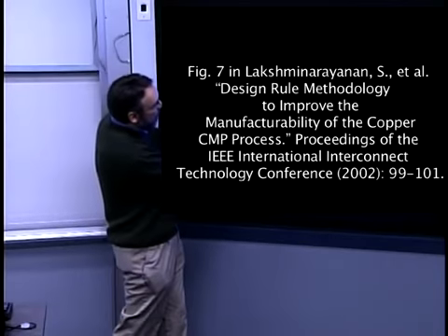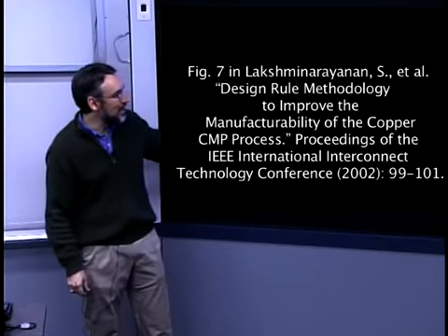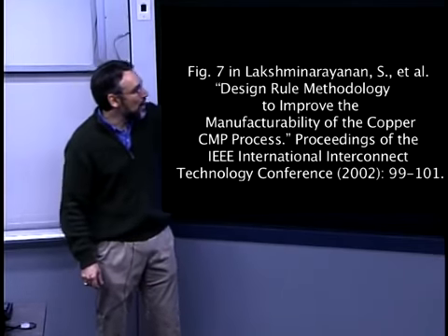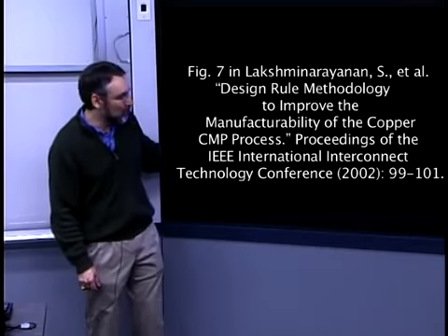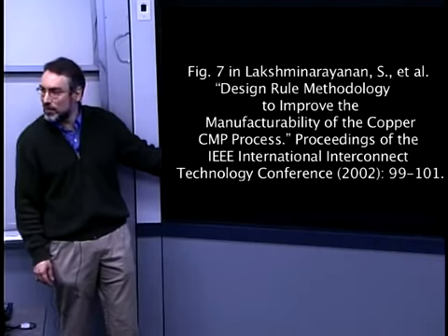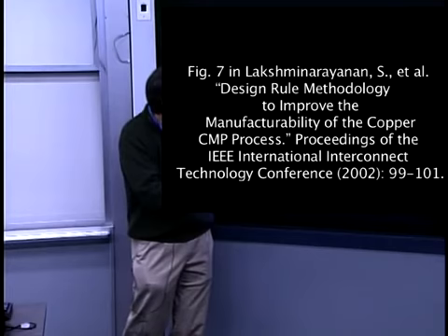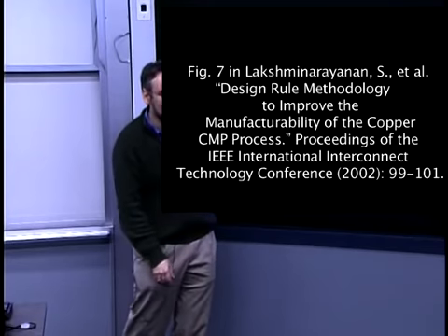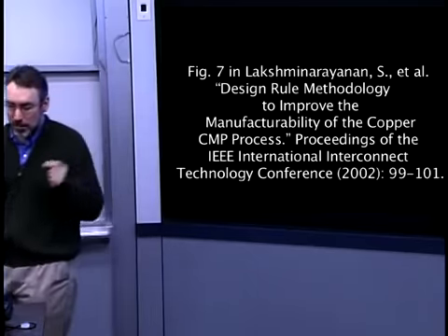okay, what region, what limits, what combinations of line width and line space can you have, and where are the boundaries because of some of these different physical effects? So, for example, photolithography says I can't pattern smaller than certain dimensions. Dishing limits, that dishing down into wide features, says I can't have features wider than 10 microns. I'll dish them too much. So this is another way of coupling between design and manufacture.